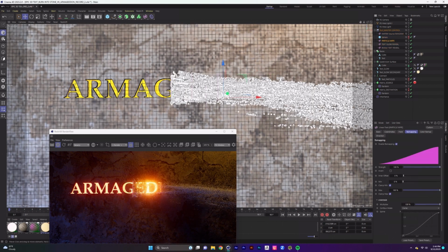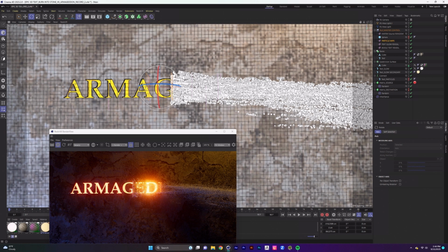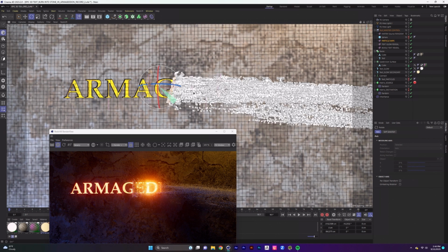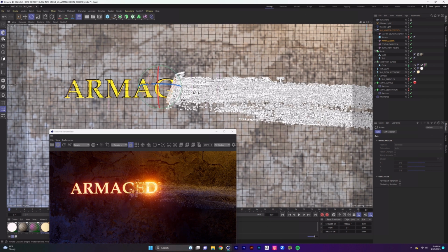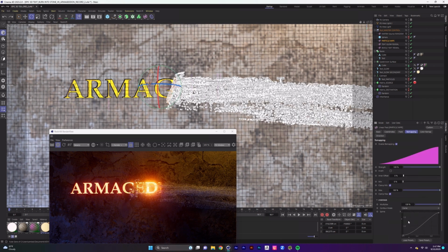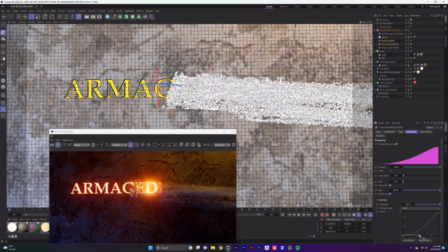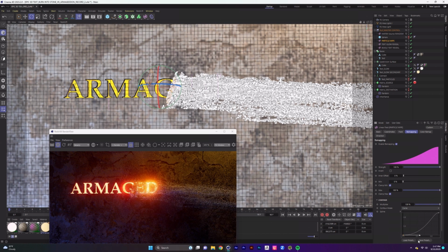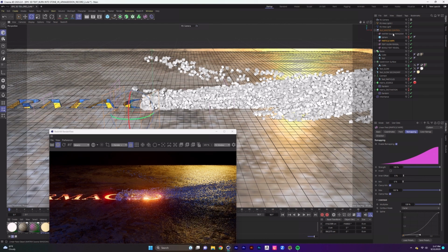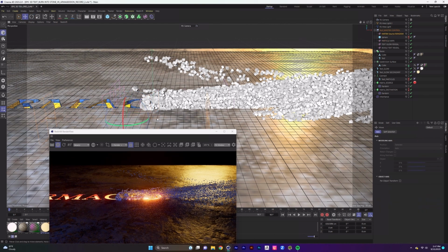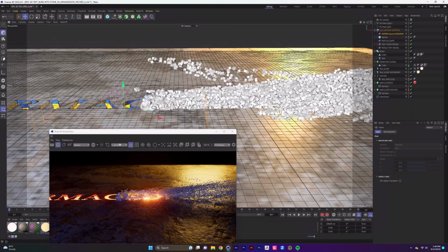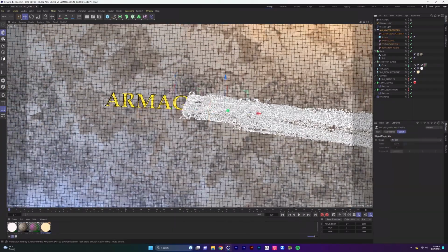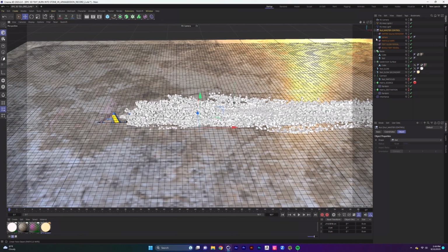Okay, now let's select the particle wipe field and we're going to rotate it a little bit so it's not so flat and vertical. There we go. And under remapping, go down to the curve we set and move the first control handle in a bit like so. This is for a more gradual move at the beginning of the particle flow. Now select the matrix source random field and move it over to the left so there's not as much noise right out of the gate. Let's actually move the matrix source random a little bit further to the left.